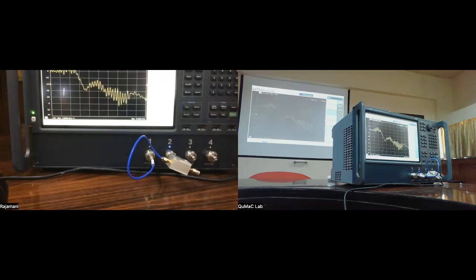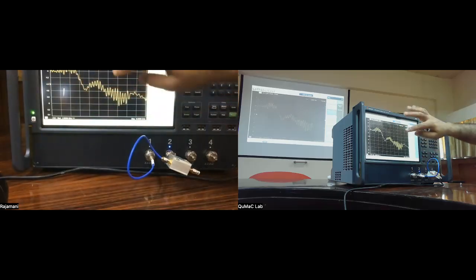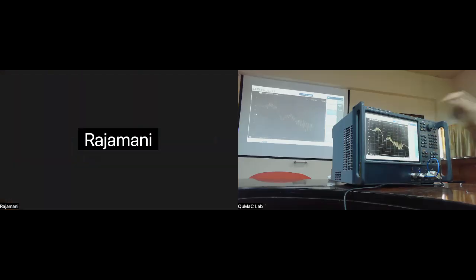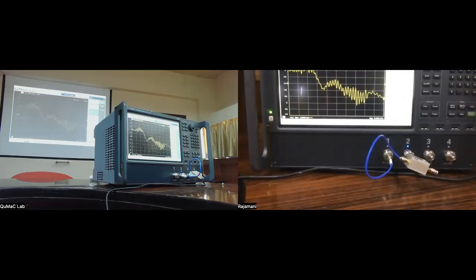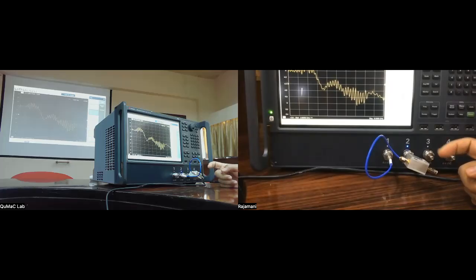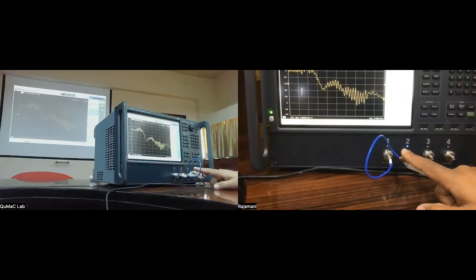You auto scale here again. And now you see that this mean power, of course, it's varying. There are some ripples, but look at the scale. It's only going from minus 5.4 to, ideally, it should be around minus 3 dB. But as I was saying yesterday, there is always going to be some extra loss, both due to components inside the splitter and now partly due to this cable.